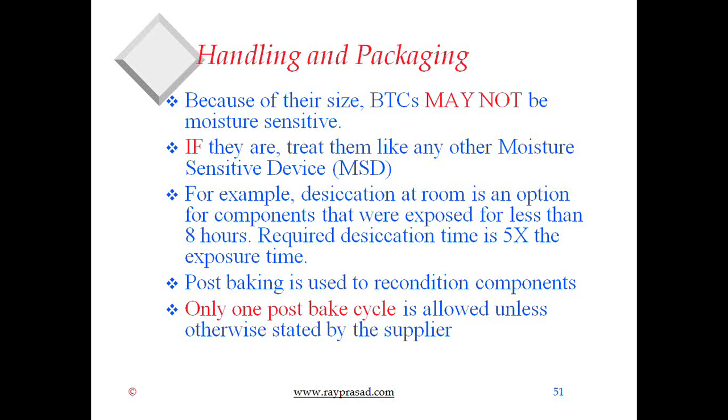In any event, that was created in 87, and of course it has been updated in the form of J standard 20 and 33. The basic problem that happens, and most of you are probably very familiar, is that moisture, when it gets in the package and goes through the reflow, that moisture will become steam, and that steam will crack the package.